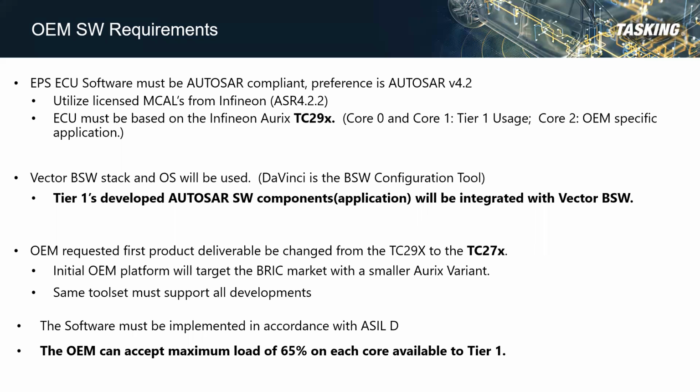If you see the specification of the AURIX TC27X microcontroller, it is a tri-core microcontroller with core 0 being the efficiency core, which consumes 30% less current. Obviously, the performance of core 0 is also reduced by 30%. The TC27X has 4 MB flash when compared to the TC29X, which has 8 MB flash. And the TC27X has 472 KB of RAM when compared to the TC29X, which has 728 KB of RAM.